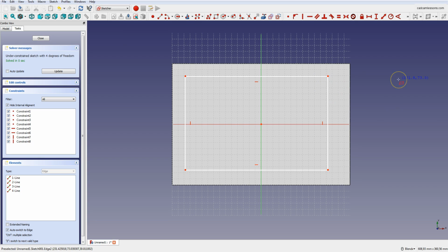Okay. We assume that we want the pocket to be offset from each side of the rectangle by 25 mm. At this point, the pocket can only be dimensioned relative to the axis of the coordinate system. We know the dimensions of the rectangular prism, so it would be easy to dimension the pocket properly. However, there is an opportunity to show the next function. This is create an edge linked to an external geometry.